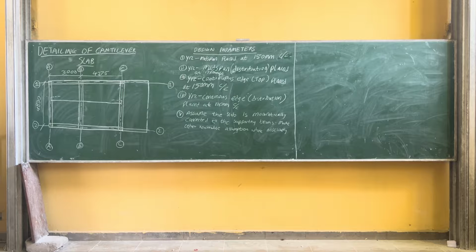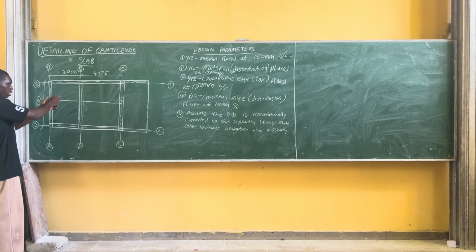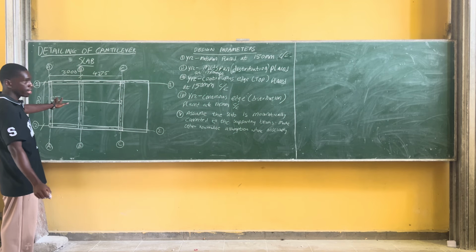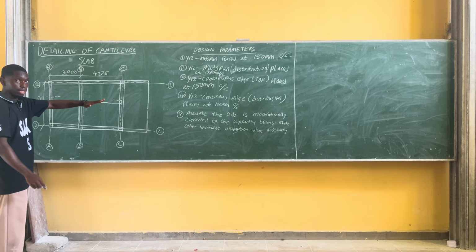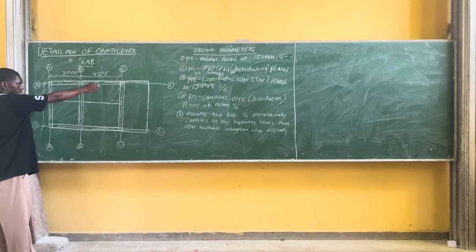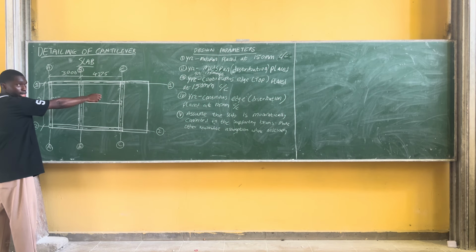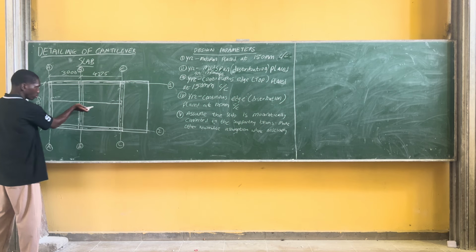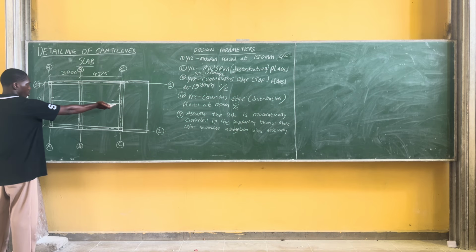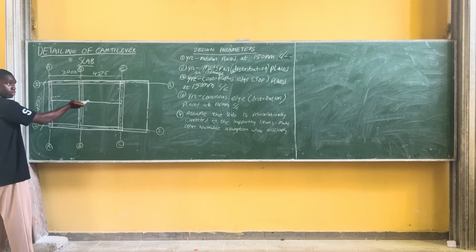Why are we putting the hook? Because normally when you're placing a hook, there's a bending, like see how the thing is for a normal slab. Why did I place it straight? Because if you look at this slab here, the main bar will be running through here. You see that? Still running like this, because it's on the shorter span. Yes, wire is on the longer span.